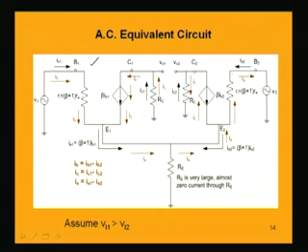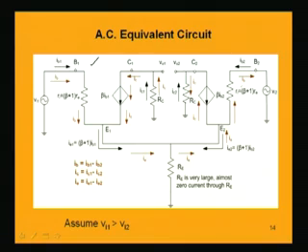and this current which flows in the transistor Q2 at the collector terminal is denoted by IC2, and the current in the emitter is IE2. The resistance in the emitter base junction for the transistor Q2 is same Ri. For transistor Q1 also it was Ri. So, same value of resistance Ri, since the transistors are matched, same beta value, and that is why Ri is the resistance between the emitter and base, and that is equal to beta plus 1 into Re,